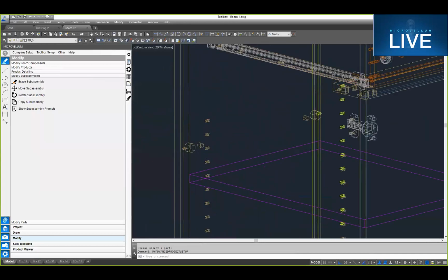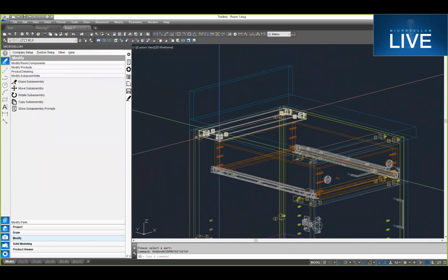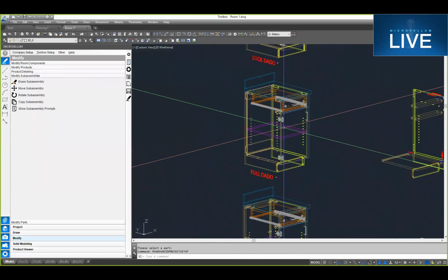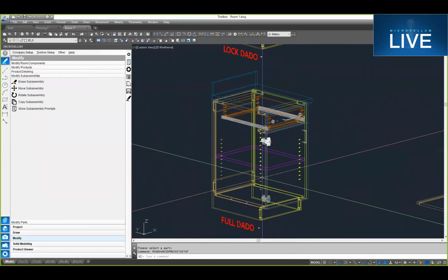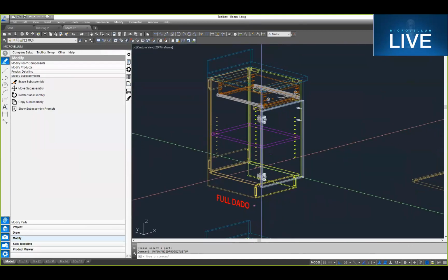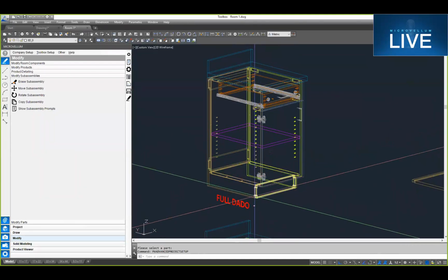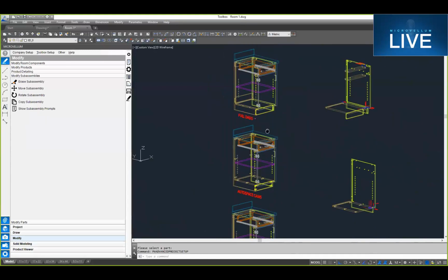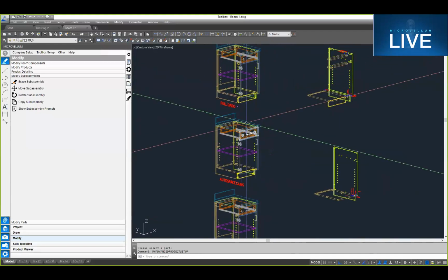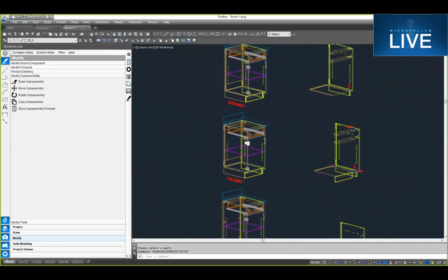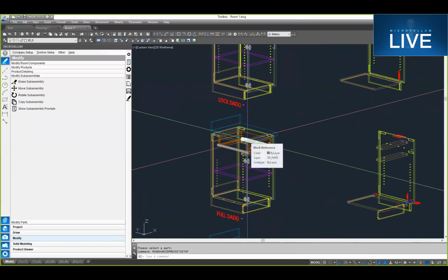Depending on which type of CAMs you're using, you can set that up to your particular construction methods. Then we'll switch over to some other more woodwork specific, I suppose. That's probably a bad term, but these are our wood joints, more so than mechanical fasteners, where dowels and screws and things are more of a mechanical fastener. The Dado construction is more of a wood-on-wood style of construction. So this is the type of construction that we would have used something like this when I was working for a manufacturer and we set up our work for the double end tenoner.